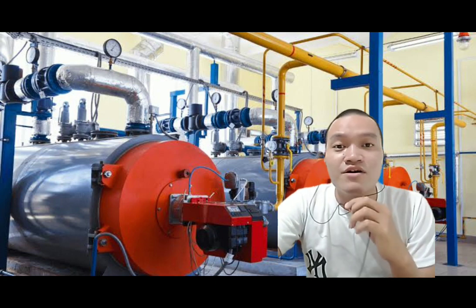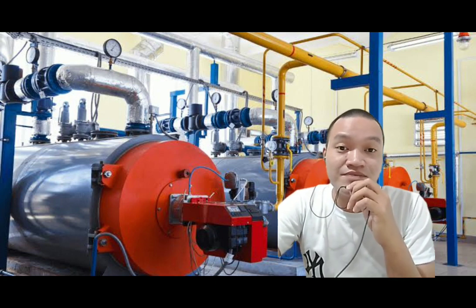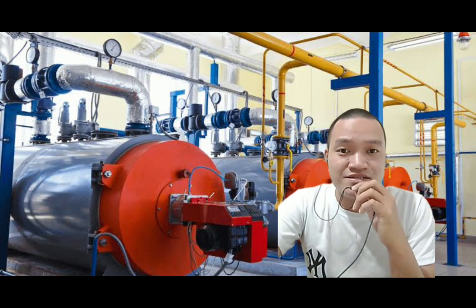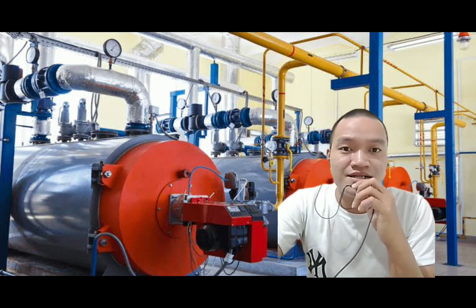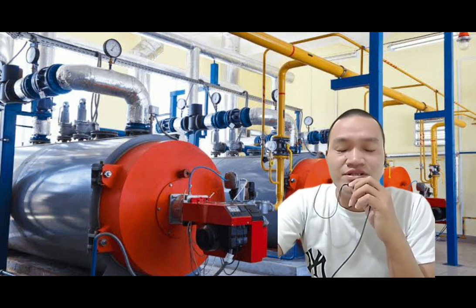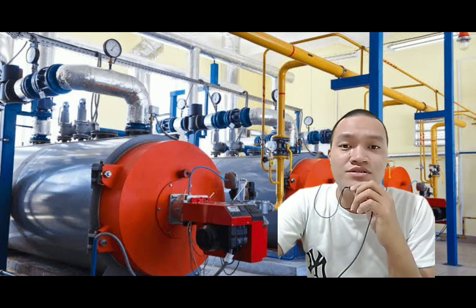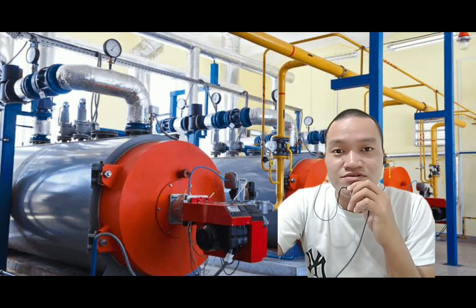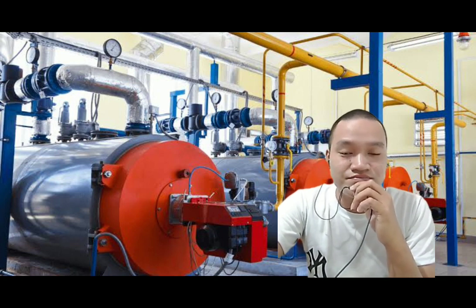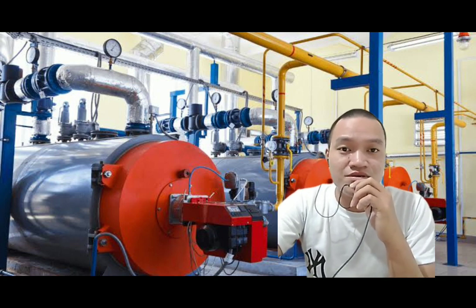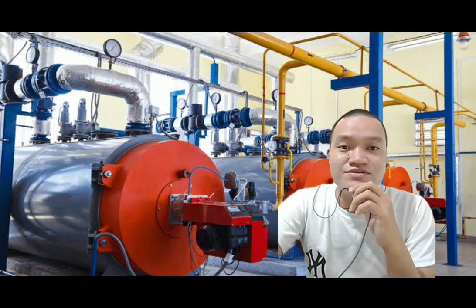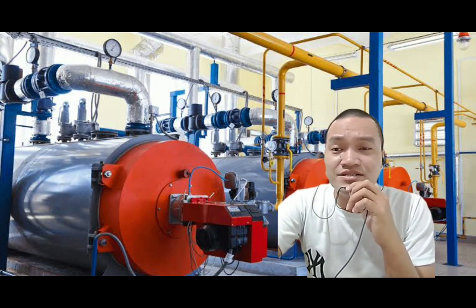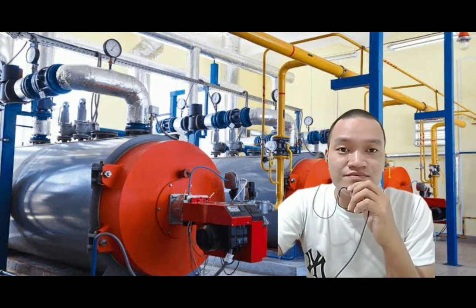So first, turn on the switches in the main boiler board. Then switch on the main switch and feed pump in the control panel. Open also the air vents and feed water valves so that the water can flow from the feed water tank to the water drum of the boiler. Then press the start button if the necessary valves are open and ready to supply feed water.